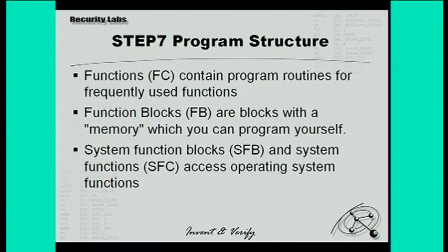There's function blocks. They're a bit weird. A function block is basically a function that has a data block, like a struct in C, assigned to it, and then it gets an instance of this data block for execution. So in PLC language, the function has memory. That's how they call it. And then you have system function blocks and system functions that are provided by the system that you can simply call. Think of them as syscalls.